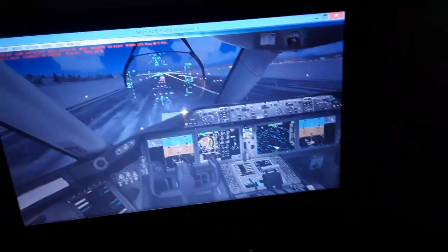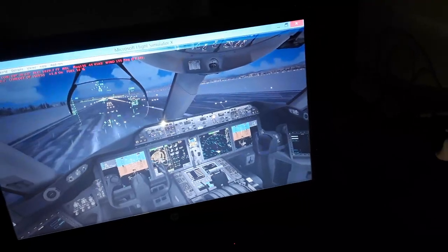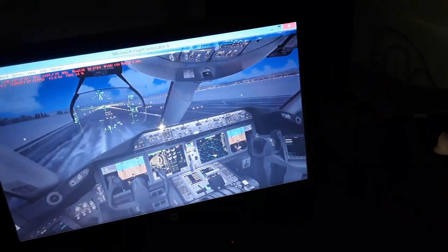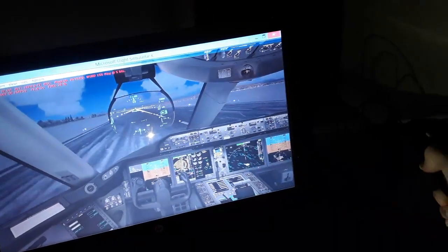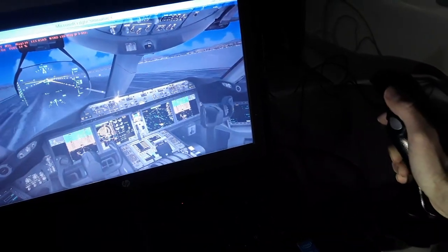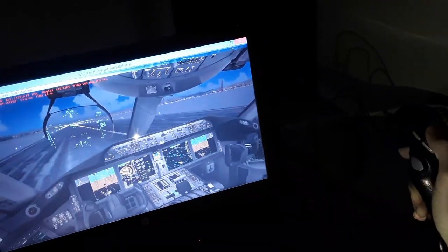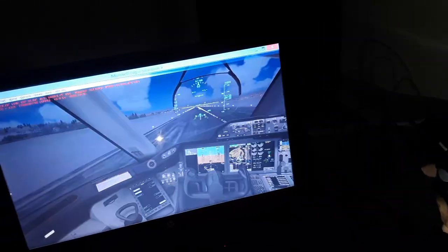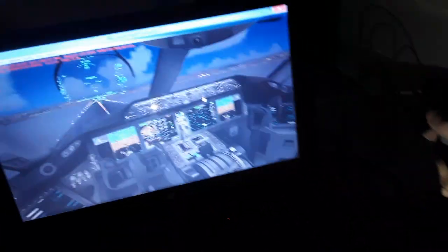So tiller like this. So we advance the thrust levers all the way up to the takeoff ground position and push down the yoke until 100 knots. So now we have like 60 knots, 70, 80, 100 knots, yoke up, 120, 130, V1 over here. We rotate 9 degrees, pitch up. So we pitch up only 9 degrees or less for takeoff rotation.